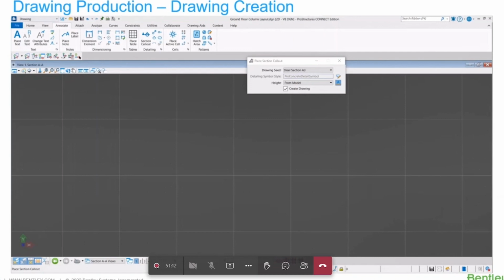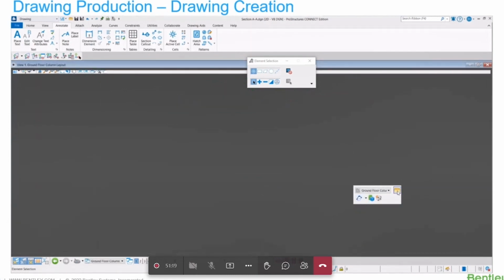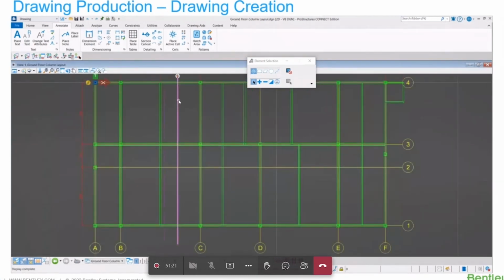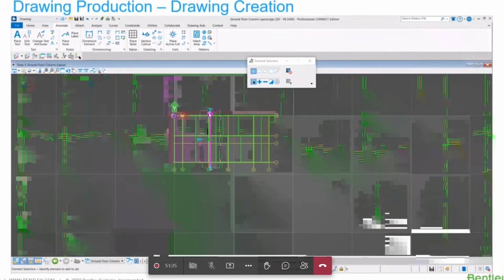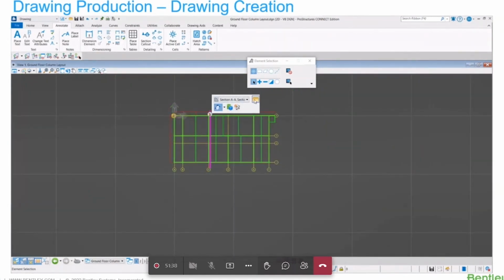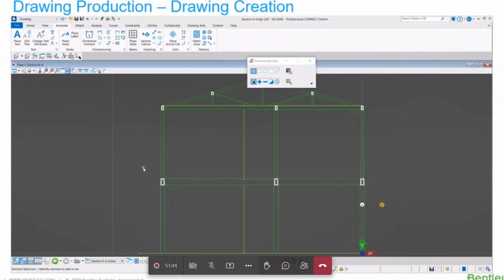And now you have section models. But if this is not the section that you wish, because the area might be different, you need to check whether there is no column in the area of cutting the section plan. So you need to move the cut area a bit to include the columns, to see the representation of the column itself. You can enlarge the area if you want to see another part of the drawing. Now, automatically, it will be updated for you as well.